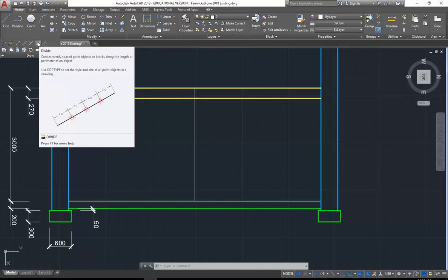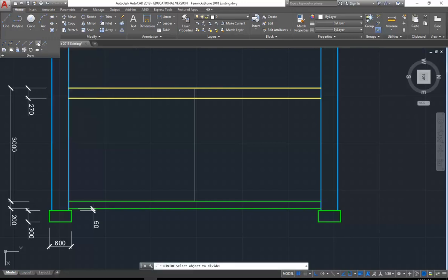So here, clicking divide, I'm going to select the line, and then we have, now let me just think, we've got 18 lines, we've got 17 segments. So just think about that. Yeah, 17 segments, so I'm just a bit rusty, just with Revit normally. So 17 would give me the right measurements, but just let me double check that.